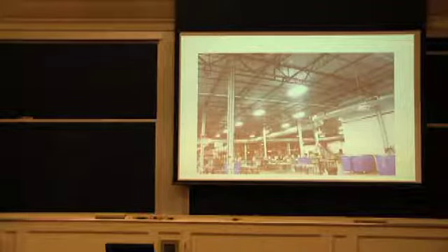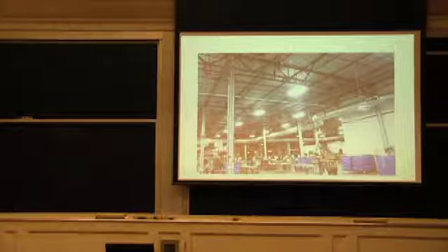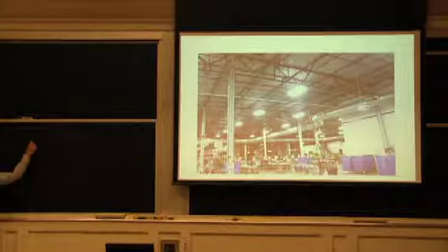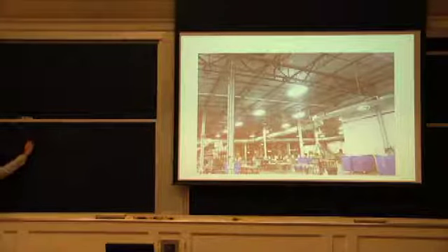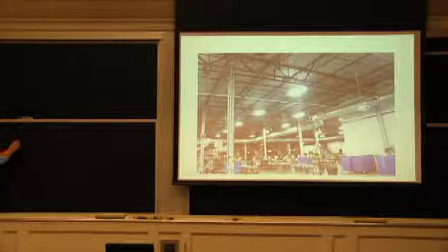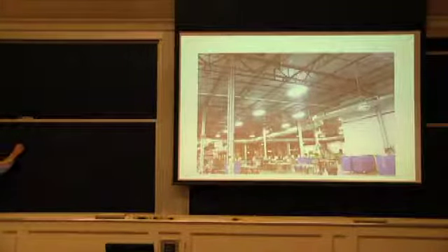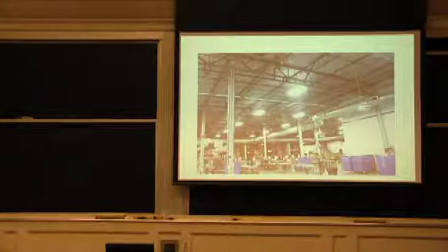Sometimes you may decide to put two diagonals up front, because that's really where you're going to have the highest amount of shear between top and bottom if these are simply supported. So it's just kind of basic structural engineering. This is not really so much part of the class, but just for your benefit, you end up with these few pieces at each end, if we have a simple support, that have a lot more load on them.